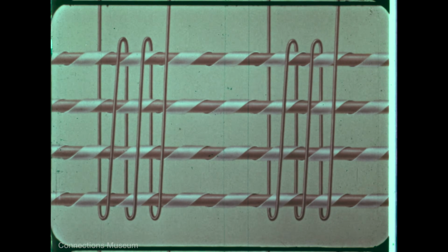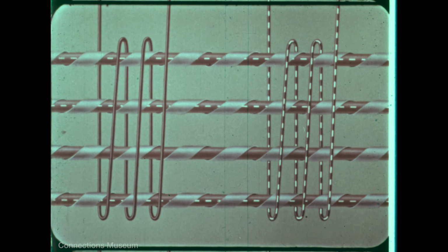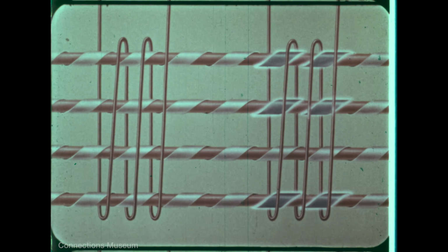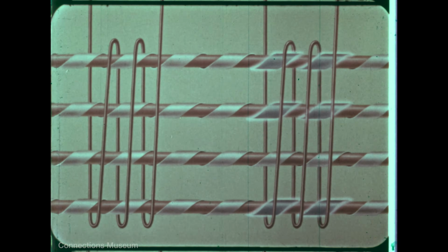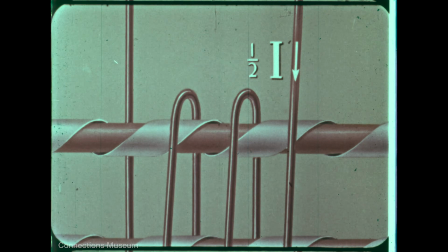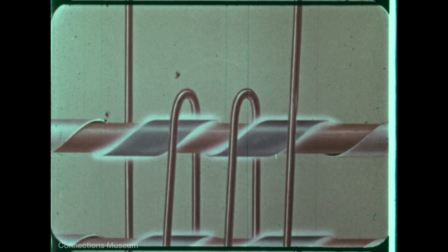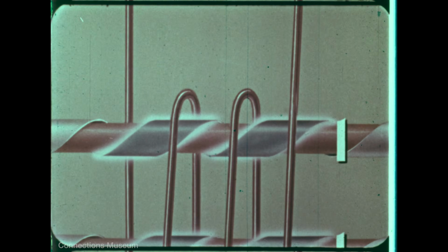In this simplified diagram, pulsing simultaneously on one solenoid and some of the twister wires will store bits in the helical ribbon at the intersections. Here's what happens. Limited pulsing on a solenoid will create a magnetic field through it that has a component in the same direction as the helical ribbon. Since the pulse is limited, the field will not be strong enough to magnetize the ribbon under a coil unless it is aided by a simultaneous pulse on a twister wire. The resulting magnetization of the ribbon represents a 1.